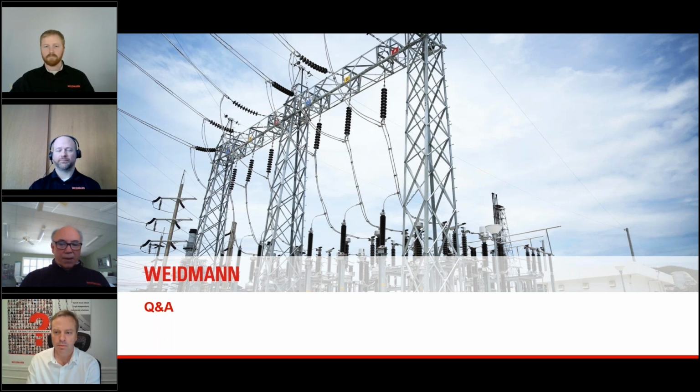Then I would recommend that you either qualify the manufacturing plant or, for some of these multi-million-dollar transformers, actually do inspections of the unit as it's being manufactured. That would be the most reliable way to make sure that you're getting a high quality transformer.